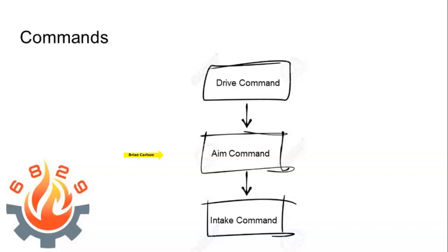So I would say having a loop in your code, doing the basic programming in the command template, is a code smell. Make sure you look at it closely. Do you really need it? Because remember, this executes every 20 milliseconds. It's easy just to do one thing in here and let the main loop that's running be the loop, and not put the loop in your command. If it's valid to be there, that's fine. Just be very careful of that.